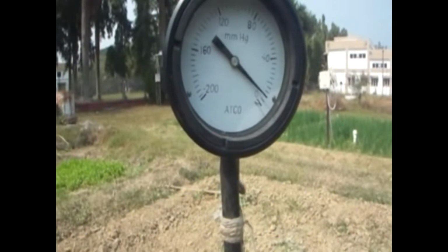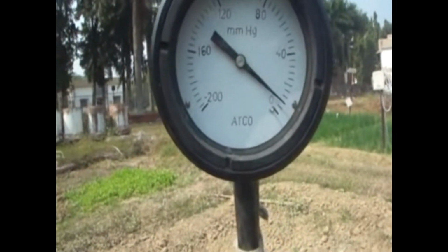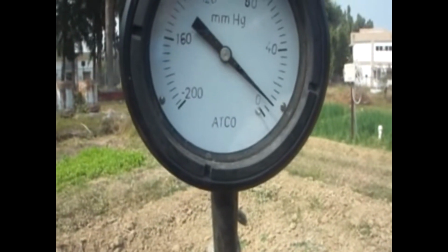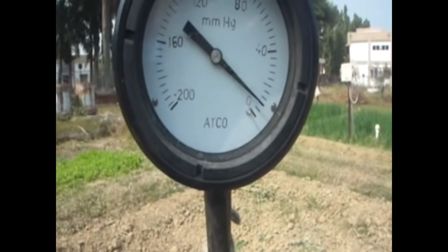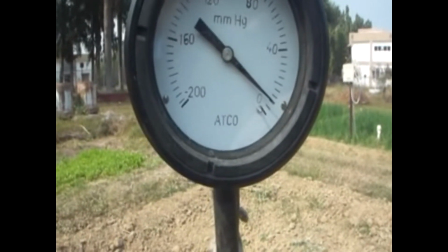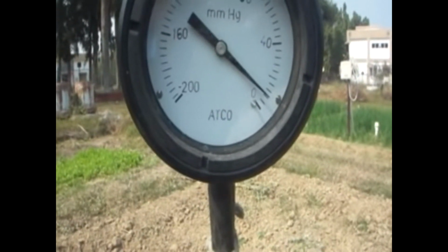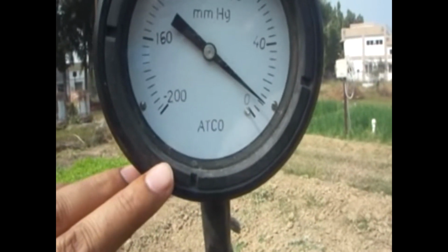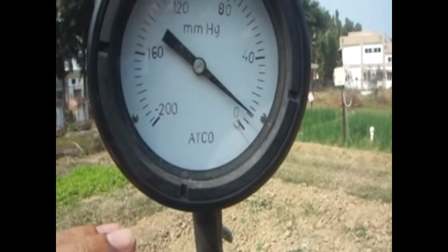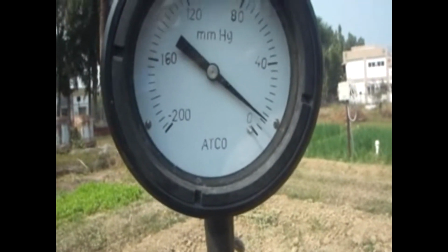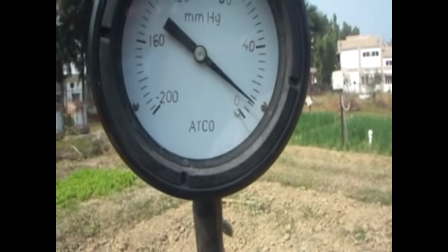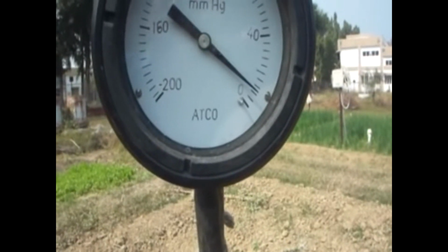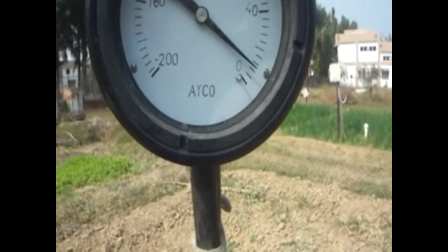Now you just see, vacuum is created inside the cylinder, and the moment the bottom air reaches the top of the soil, it bubbles and it will start decreasing this negative pressure. So pressure will increase. So now it is reducing the pressure inside. It is showing the air pressure at the bottom, the air entry pressure. The moment air enters into the cylinder after crossing this whole layer of soil, it will start increasing the pressure.